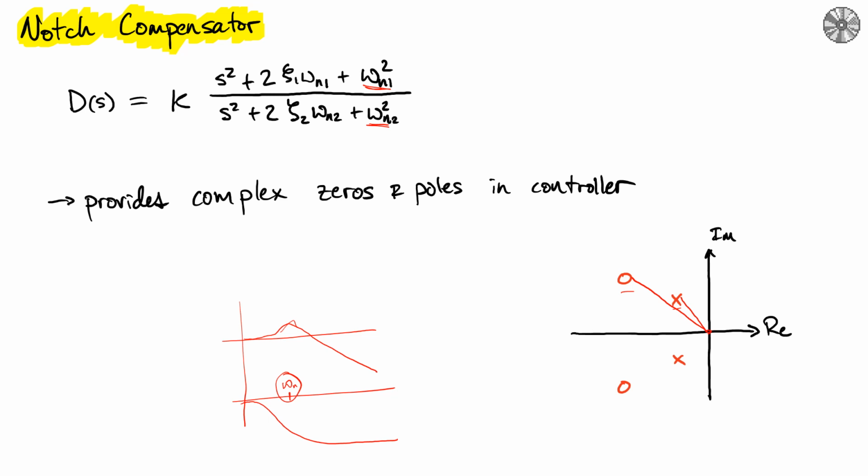And then the damping is what makes this notch particularly peaked, or this slope particularly steep. And so depending on how you select those, you can get different shapes, but they're kind of a perturbation on the same theme as a lead and a lag compensator.